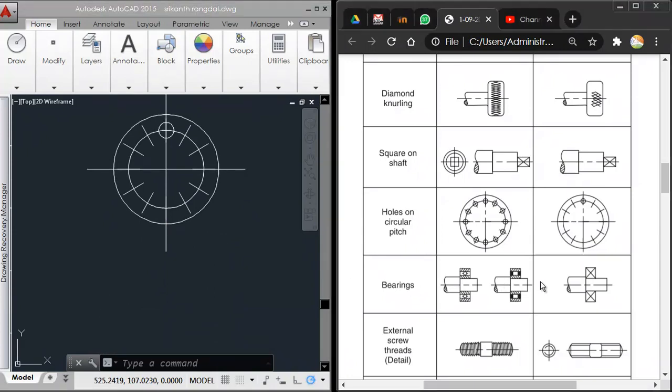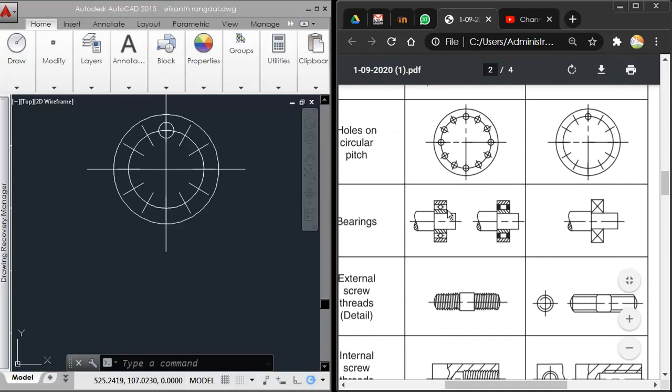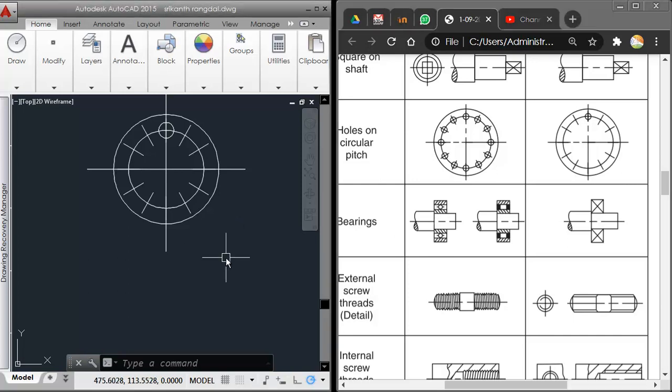Next, coming to the bearings, you can see here the bearings look like this, and they may have circular balls present within themselves, or they may have cylindrical balls like this. Cylindrical balls, because they have line contact, they have greater ability to take more loads, whereas the circular ones are slightly more smoother. So it depends on what kind of bearings you want to use.